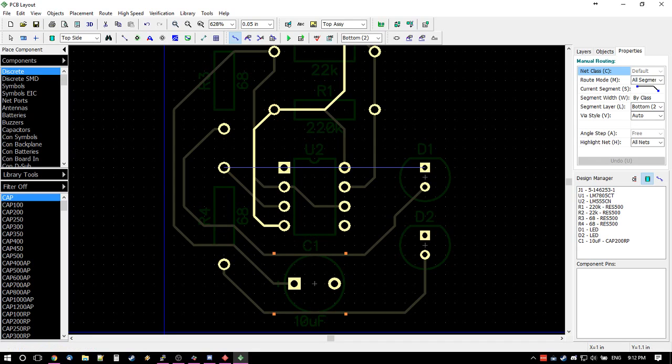So now those are connected together. So you can see the way they're connected together is that pin is connected to this resistor, which then comes up through the hole and to the other one. Then last but not least, we're going to connect this diode all the way.